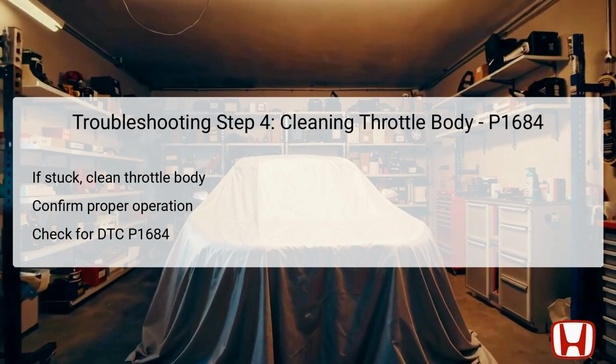This confirmation step typically requires repeating the initial engine startup and RPM holding sequence to ensure that the throttle valve is now functioning correctly. If after cleaning, DTC P1684 is not indicated, the issue has likely been resolved. Otherwise, further inspection of components related to the throttle body, including electrical connections to the PCM, becomes necessary.